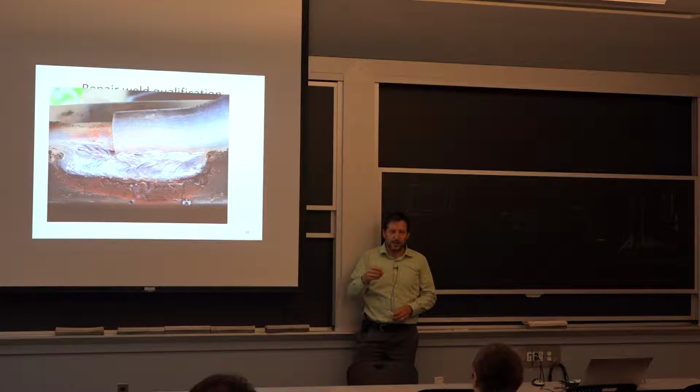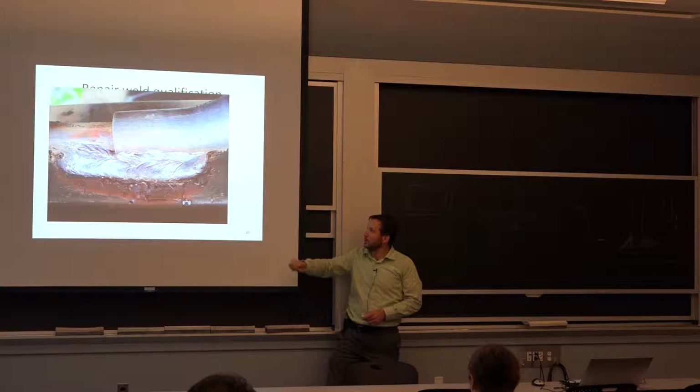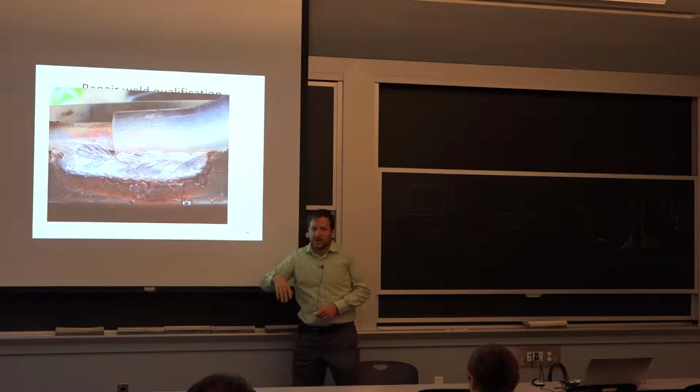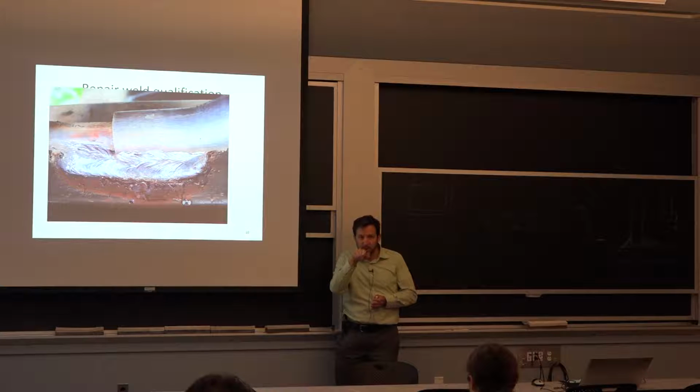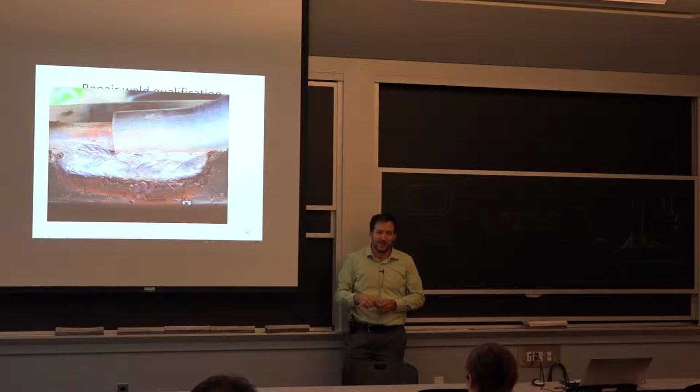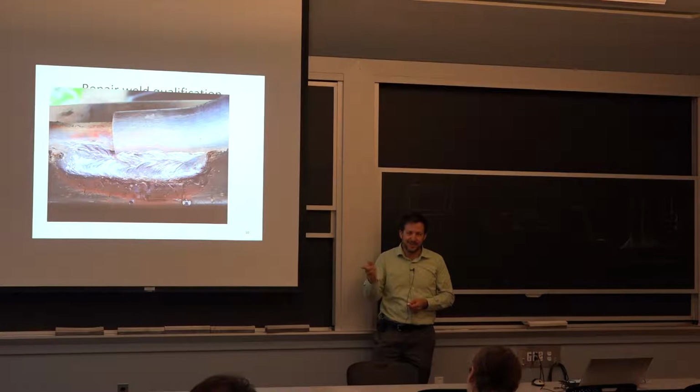This was the best welder they had there. He used to do a lot of high pressure vessel, and you could tell he was weaving a little bit. And that's what you need to do for this type of joint, because the two pieces are pretty apart from each other. So unless you purposely transfer the heat on one side and the other, if you try to put it just in the middle, well, that's not where you're going to weld anyway, so something else is going to happen. So I was actually telling the younger welder, look at him, look at what he's doing, because it wasn't excessively hard, but it made all the difference in terms of passing all the qualification tests.